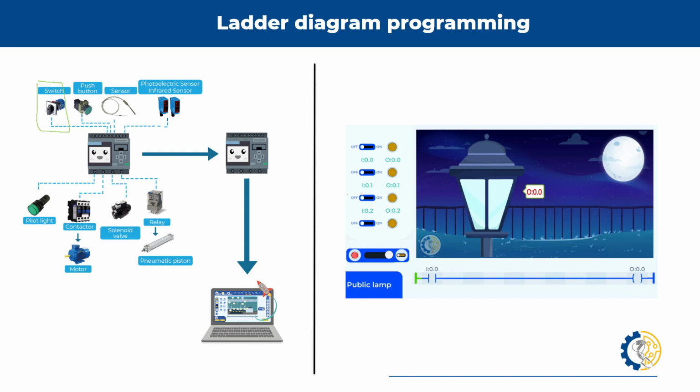With my switch, I can control this pilot light. If I didn't have anything programmed, whenever I'm energizing this or powering this, it's not going to indicate a thing because I wouldn't know what to do. But if I create my line and I add my condition with my selector, that if I get voltage and I'm getting this signal, then now I'm going to get my lamp.